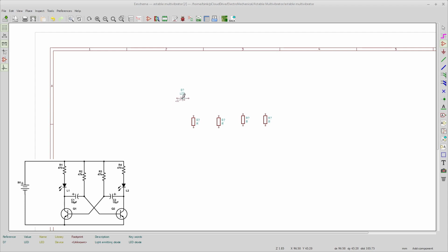So that if you want to make these little test boards, you want it with the LED and you want it without the LED. Sure, we could probably put a test point in before the LED or something like that just to get a signal out of it. But the LED is probably going to mess with that a little bit if we wanted something more pure, maybe. But anyways, what we can do is we can stick this on the edge. We can make a little solder jumper and bypass the LED. Well, I'll explain as we go.